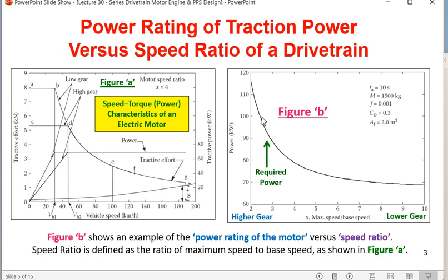Whereas whenever you are in the higher gear, at that time to create the same amount of acceleration, you have to utilize more fuel from the engine. So this is what this graph is all about. For higher gear or lower value of x, we have to give more amount of energy to cause an acceleration, whereas whenever we are in the lower gear, to cause very big acceleration we have to use very small amount of energy, because the vehicle is already in a high torque mode. In high torque mode, acceleration is easy.